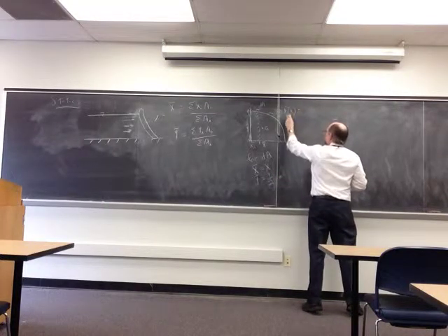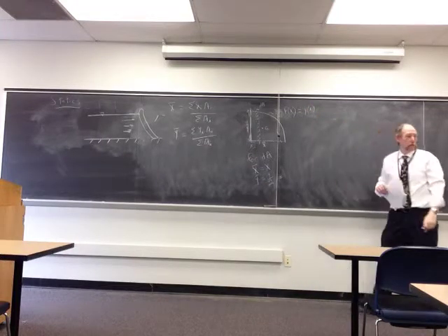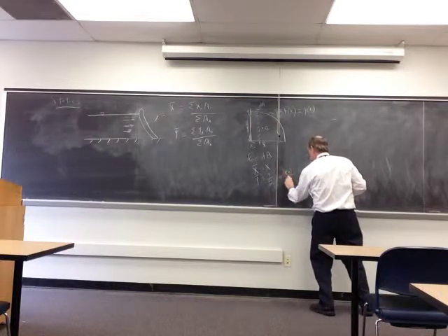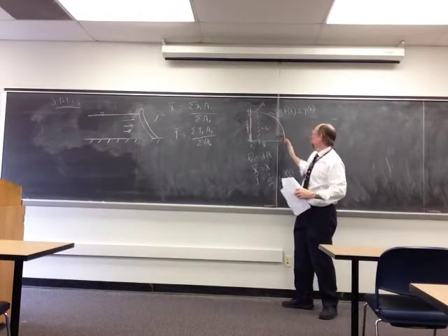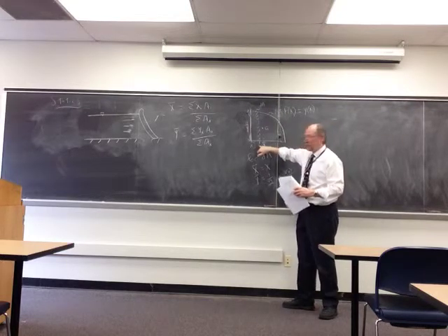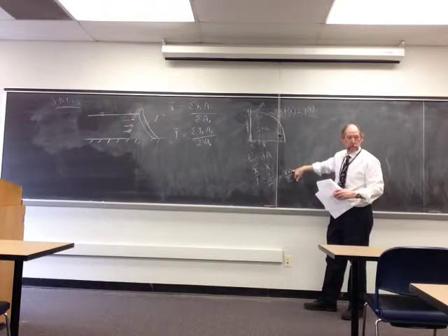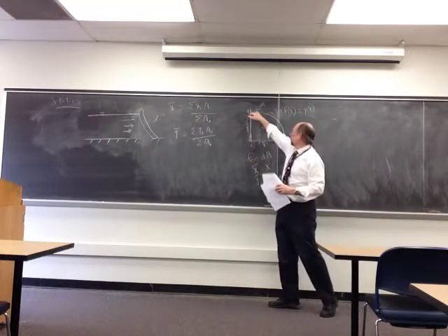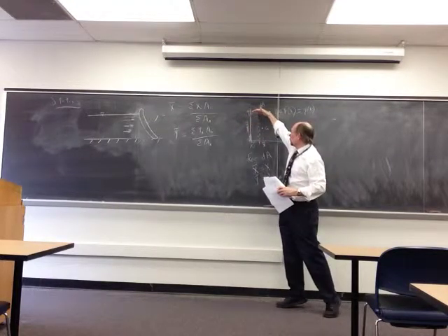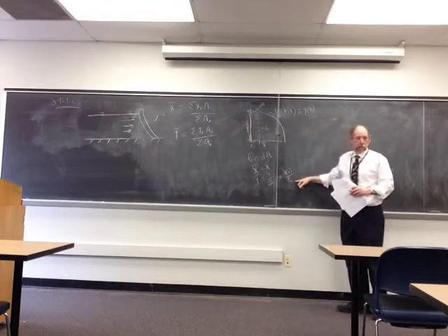So whatever equation defines this line, if you evaluate it at this value of x, you get y of x. That's the top of your rectangle. The centroid is going to be at the midpoint, so it's going to be y of x divided by 2.